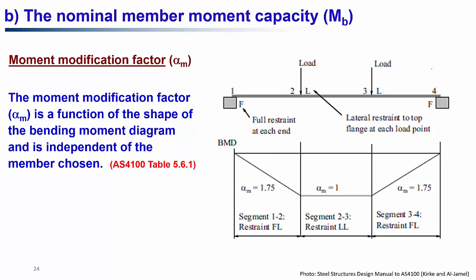Because our lateral torsional buckling equations are based on a constant moment throughout the section, right? When the beam has a constant moment throughout the section, then one flange will be in compression uniformly, and the other flange will be in tension uniformly, right? So in that case, the buckling will be uniform throughout the section, but that may not be the case all the time.